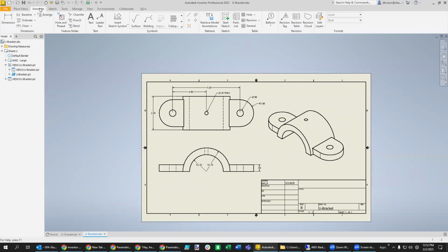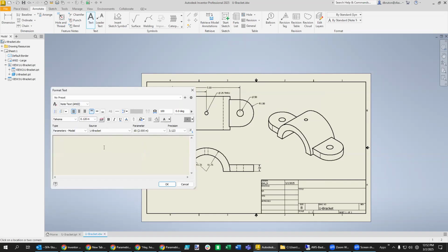So what you want to do in this case is on the annotation tab, select text, and just highlight this whole box like that. And we'll pick a good size font that makes it look good. So we're going to type in the name of the university. And we can highlight that text and we can see what it looks like over here, kind of a preview. Let's show it middle justification and center on the alignment. And then maybe highlight this and put 0.4.